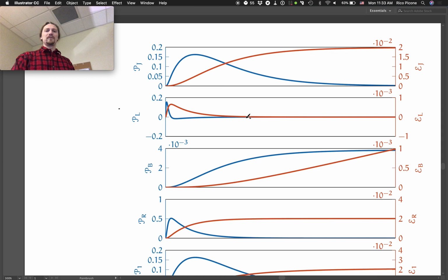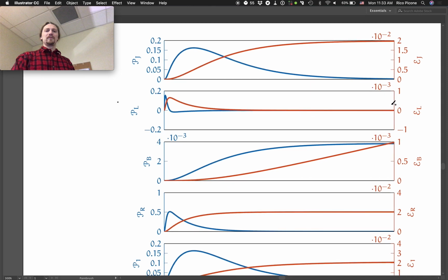In an ideal inductor at least, it doesn't generate heat. It just flows the energy back into the circuit. So that's what the inductor does. It stores a little bit of energy at the beginning, and it releases it back in. And then by the end, as Robert pointed out, when you're in steady state with a DC supply, it shouldn't be doing anything. It doesn't store any energy when you're in steady state with a DC source. It just looks like a conductor.